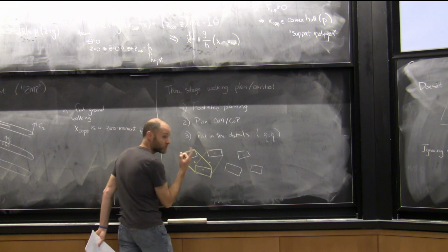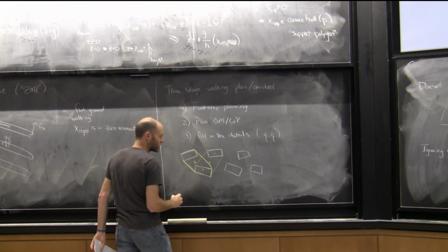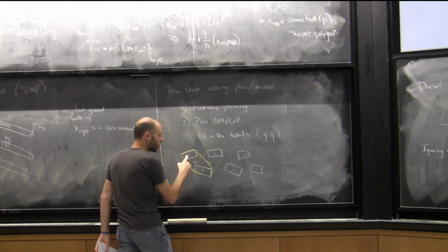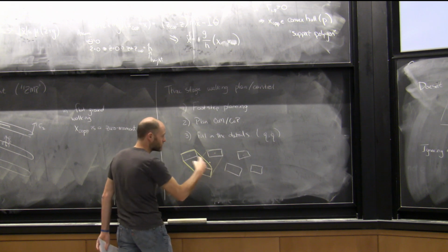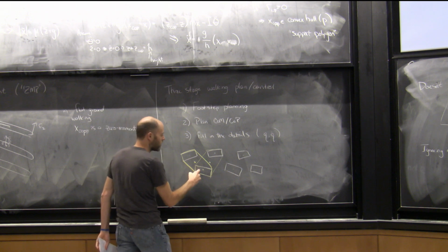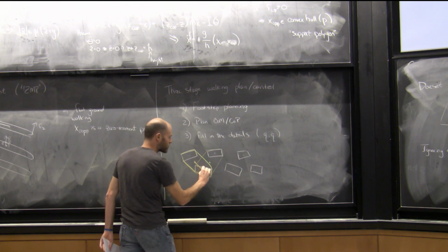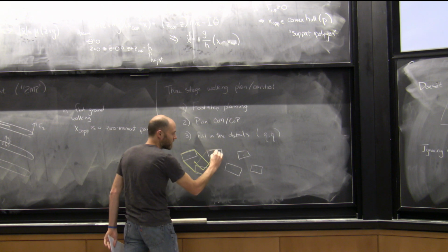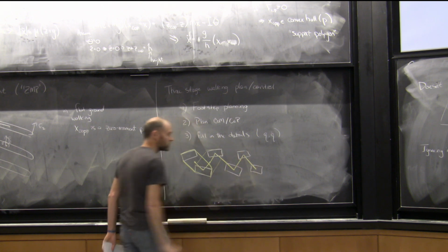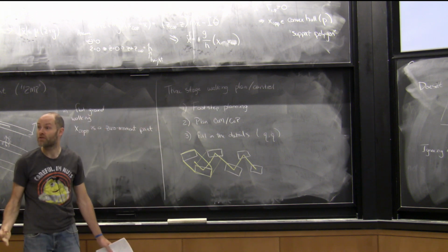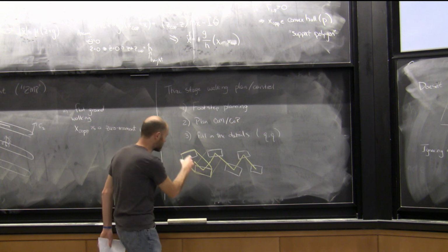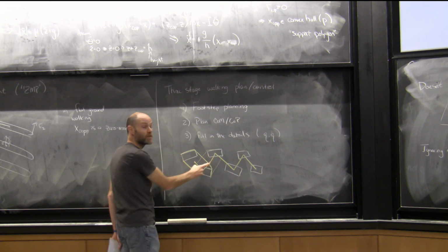So what people used to do, and for a long time got very far, all the initial Asimo videos, they said once I had a footstep program, which was a trajectory of locations and timings of my footsteps, then I could actually just draw the straight line center of pressure trajectory like this. Just say my center of pressure is going to follow that. And you have to prescribe the timing so that it gets here before you lift off this foot, and you get here before you lift off this foot.